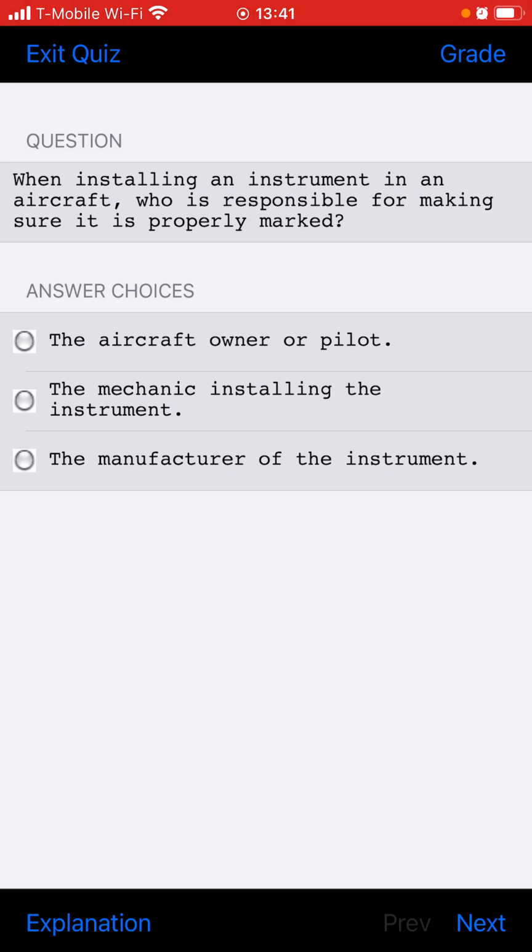For what reason is the fuel jettison system usually divided into two separate independent systems, one for each wing? To help maintain lateral stability by jettisoning fuel from a heavy wing if necessary.